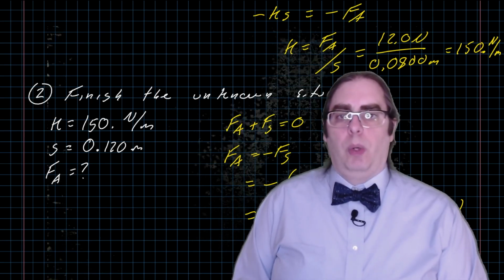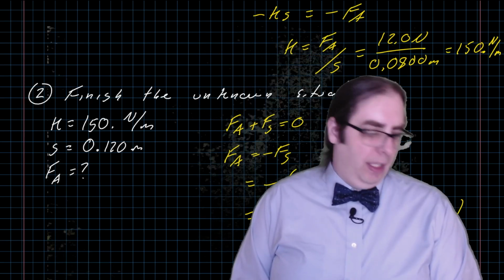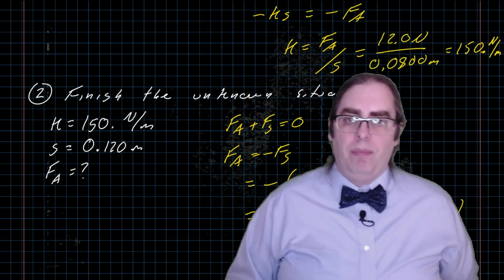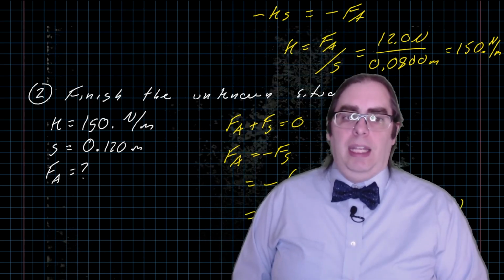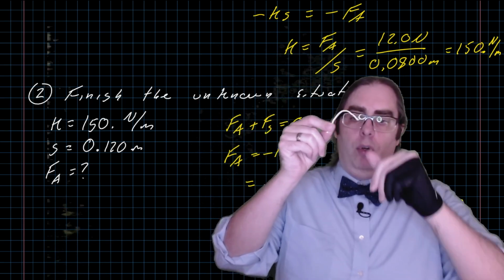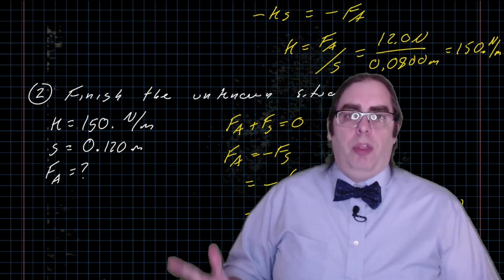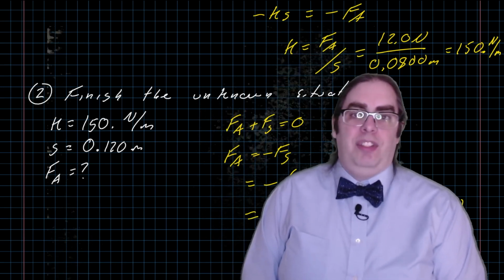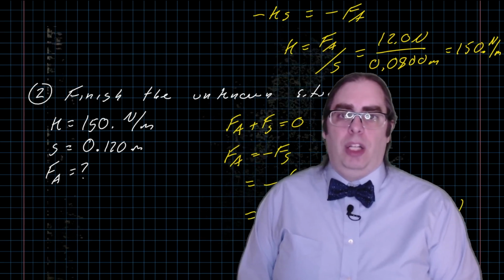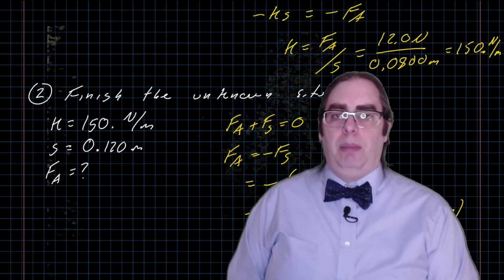The last thing I'm going to say before we wrap up is it is amazing how many things can be modeled as linear springs. Springs do not have to look like a slinky with the coils of wire that are jumping up and down. A leaf spring is something a little bit closer to that little bit of bent wire that I was looking at before, where this one has a very, very small spring constant, but you can get them to be stiffer. You can also model things that are not spring-shaped at all. Right? A steel beam, in a lot of senses, is a spring. If you're applying forces to a steel beam that might cause the beam to deflect or compress or stretch, it's going to behave as a spring within at least some regime of possible forces.